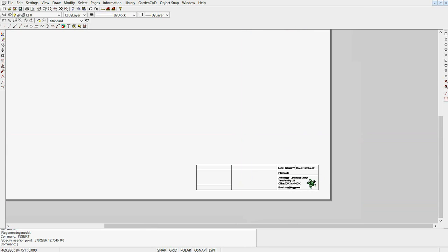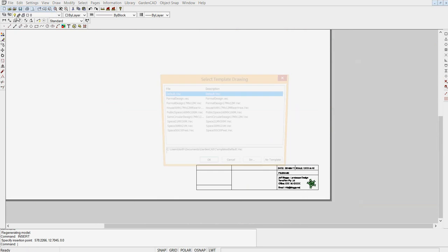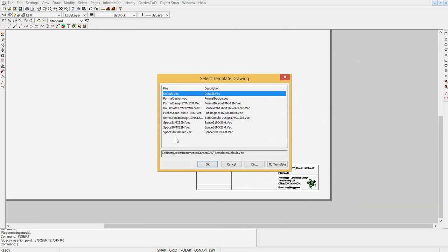becomes much more versatile. Now if we can put the title block into a template drawing, we'll have a very powerful way of doing new jobs. We would just say file and new, up would pop our list, so we'd have our company, the name of the file could be company project would be the template drawing. It would already have the title block in it, different sheets and different pages, and all ready to roll.